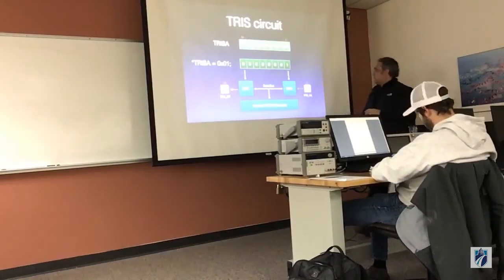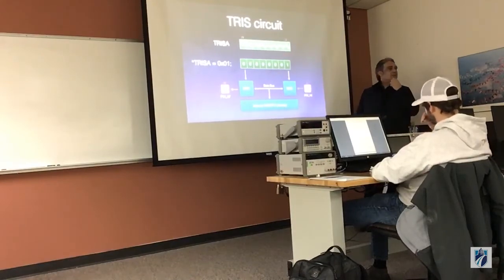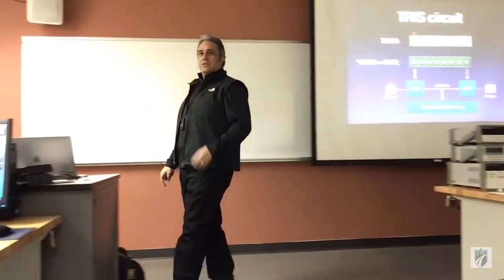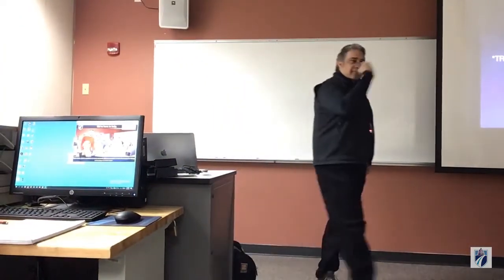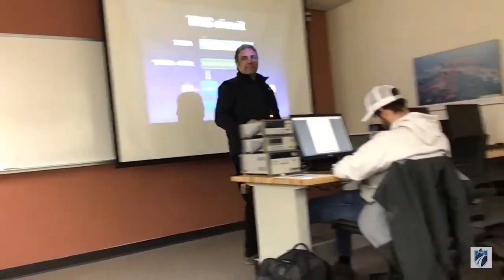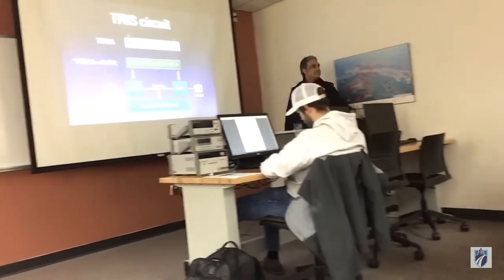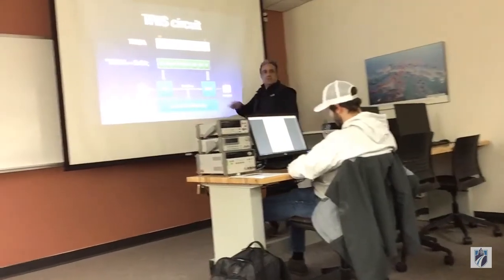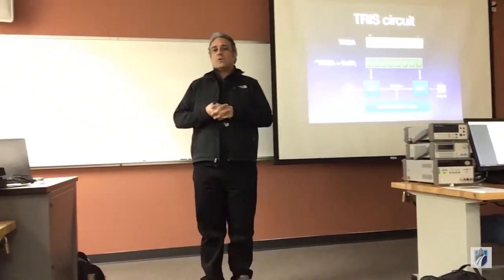symbols. Look at this symbol in particular. It's a square box with an X through it. In the microprocessor world, that means that this is an actual physical pin. I can access it and visually see it. It's telling me that this is physically a position. So when you're reading schematics, and you see that box in your data sheet, they are telling you this is a position that you can get to.